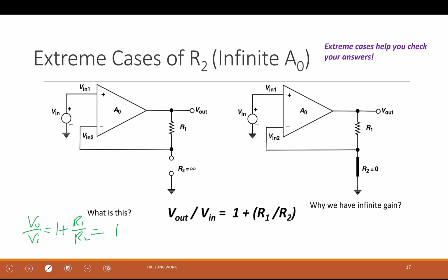The reason a resistor has effect is because you have current going through it. Then it causes a potential drop. If there's no current, there's no difference between having a resistor or not, right? Do we have a current going through here? Exactly. Because of the infinite input impedance, there's no current, right? So V out still equals V in minus. Then all the derivation we did before is still valid. So this is just a buffer.